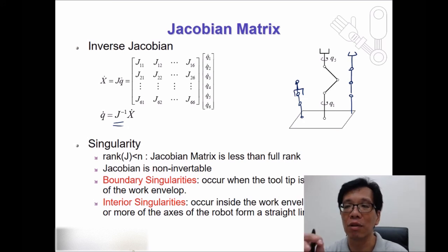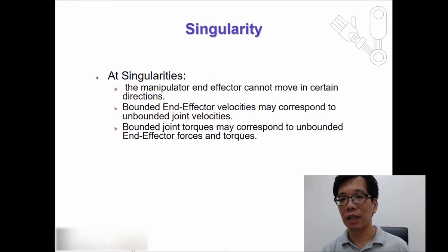So when it's singular, you need to be careful to figure out the geometric configuration of the structure at this moment, because you might damage your system, or you might overturn some of the joints and break the joints or break some sensor. So when you have that kind of situation, check the physical setup and ensure you are not going to damage anything before moving on.